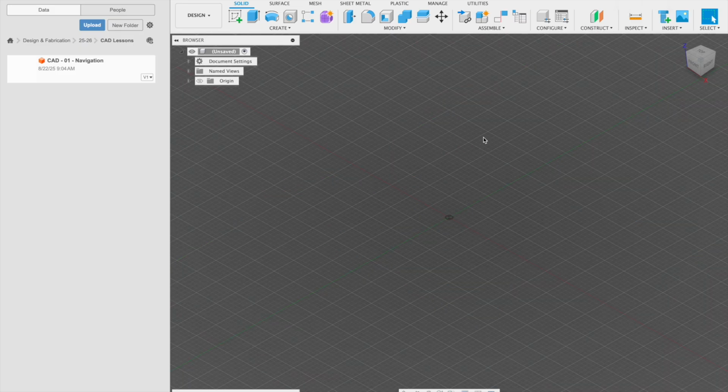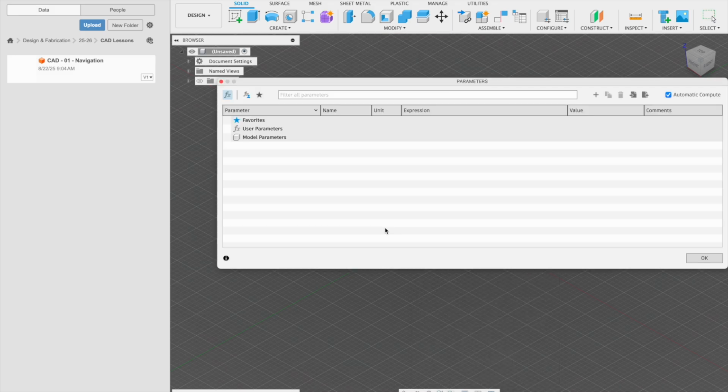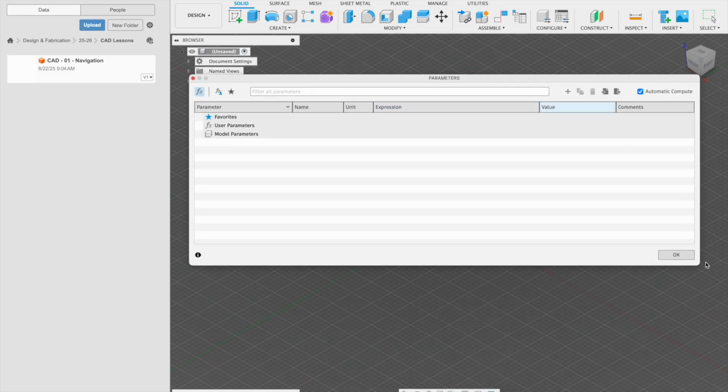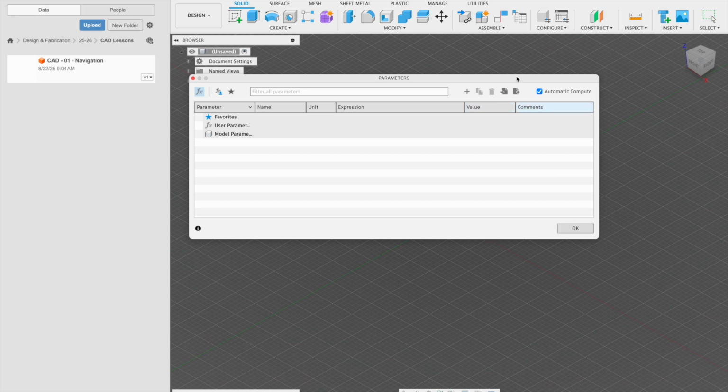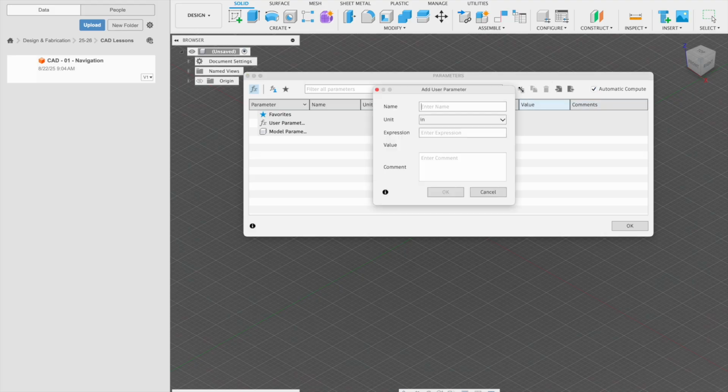And we're going to leverage one of the most powerful things in Fusion 360, which is that we can set parameters. Parameters, if you think about them, are something like variables. So let's say that we don't necessarily know how big we want this thing to be, or we want to change our mind down the road, or we have something that's flexible. So we're going to add a parameter. We're going to need to name it, kind of like a computer science convention, as board width. And our board width is going to be 7.5 inches and hit OK.